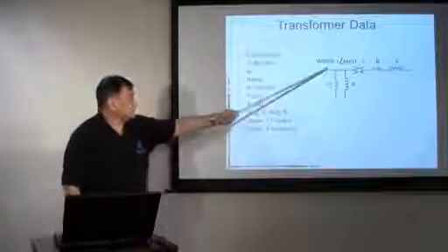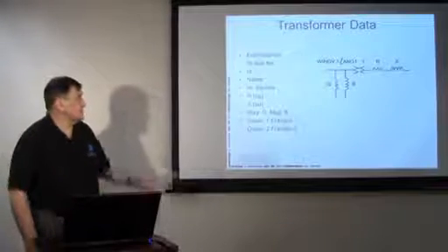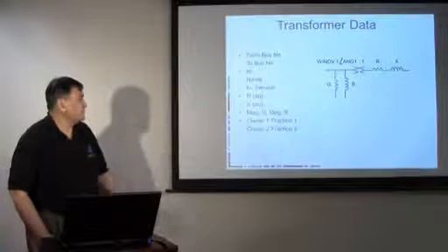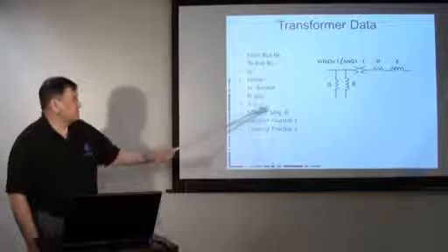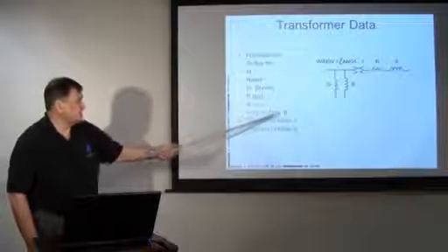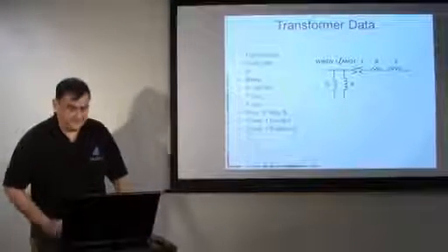Again, it's a two-terminal device, has a from and a to bus. It has an identifier and a name, a flag to show is it in or out of service, resistance, reactance, the charging, the magnetizing, and then a fraction for its ownership.